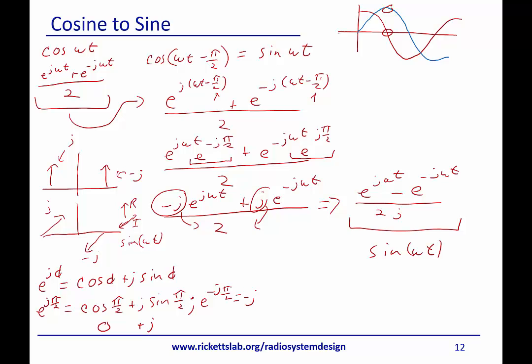And once again, both sine and cosine are absolutely real. It's just they're orthogonal to one another. Sometimes when we're dealing with complex numbers, that complex number just allows us to deal with an orthogonal component. And so what we can see is this phase shift actually just takes this, rotates it down, takes this, and rotates it down. And using that now we can get some insight into what phase shifting a signal might do